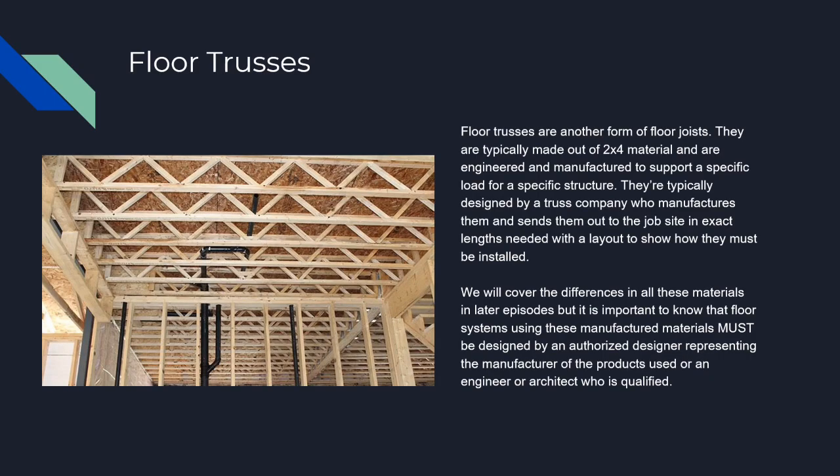Floor trusses are another form of floor joists. They are typically made out of 2x4 material and are engineered and manufactured to support a specific load for a specific structure. They're typically designed by a truss company who manufactures them and sends them out to the job site in exact lengths needed with a layout to show how they must be installed.